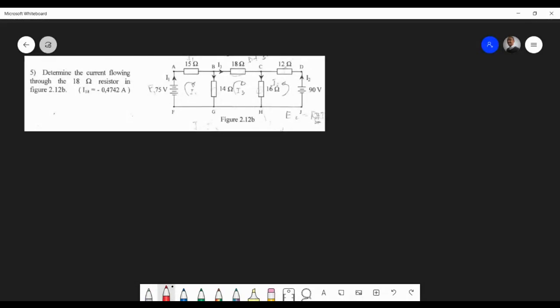We can assume, sir, I4. Yeah, I know, but what is it if you're looking at I1 and I3? Using Kirchhoff's, that's going into that point, that's coming out. Wouldn't you say it's I1 minus I3? Yes, that's what I'm trying to say. You can say I4, but we want it in terms of I1, I2, and I3. This is the hardest it's going to get, by the way. If you can do a problem like this, you'll be okay.